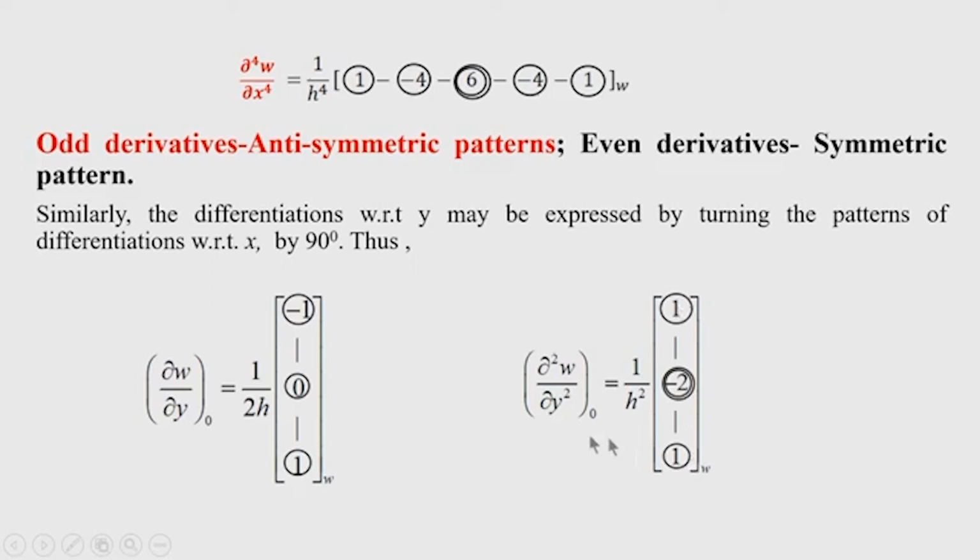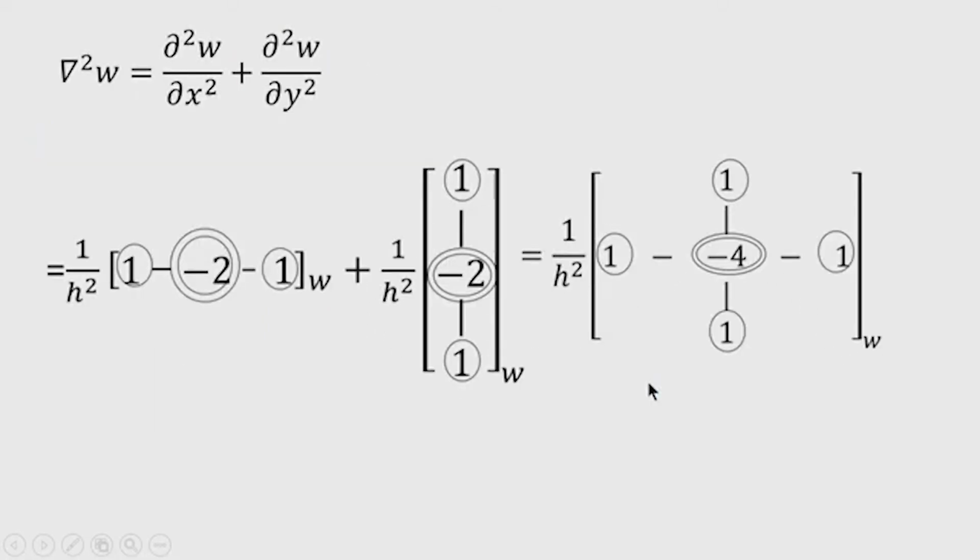Okay. So, horizontal direction is x direction and vertical direction is y direction. So, it is written like that. Then the Laplacian operator, that is del square w, we need sometimes, because under biaxial compression, where an equal amount of compression is applied in both x and y direction in the plate, you will find that this Laplacian equation is necessary.